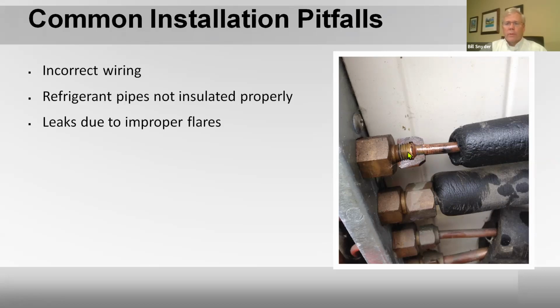A proper flaring tool is highly important. Don't use your old Imperial Eastman that you got 20, 30, 40 years ago. Use a good quality R410 flaring tool that rolls out the flare. Don't use the ones you put on a drill bit. They're not good. They don't do a really good flare.